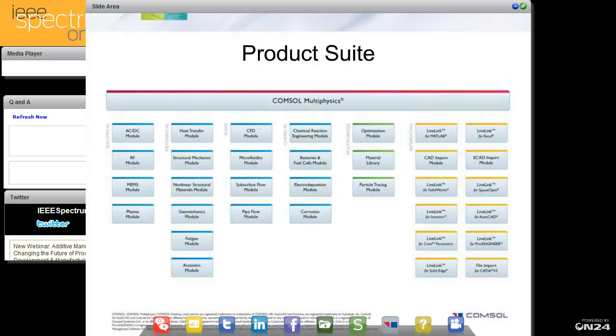Okay, great. Another question about the billet. The billet conductivity will affect skin effect. How does the model handle this and factor in reduced conductivity at the high temperature? What you typically do is that you introduce the temperature dependency on the conductivity, and in this particular model we can use, for instance, a linearized resistivity model, or we can use empirical data in the form of a lookup table.